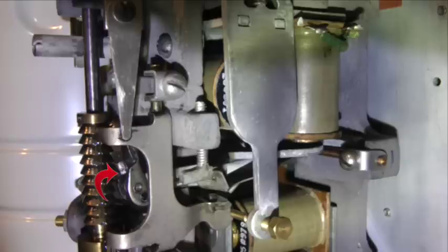This is the vertical pawl. It is attached to the end of an arm of the vertical armature. Each time the vertical armature operates, the pawl engages a vertical ratchet tooth and pushes the shaft upwards by 1 step.